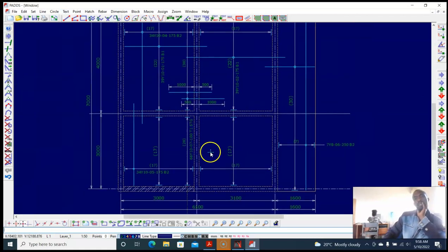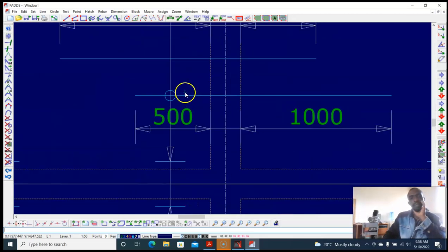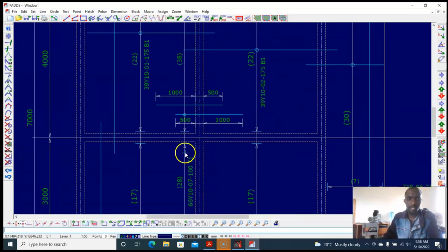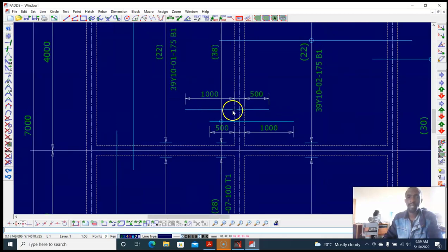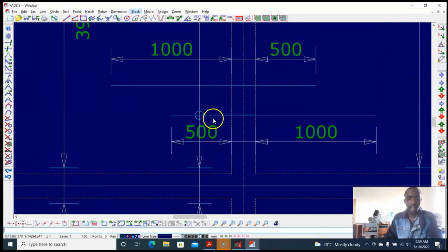Staggered. Repeat how you include that one and how you edit the text. We were at that point. This dimension line is picking this rebar, but it's not capturing this other one. So I type BB, pick this, click here, click there, B3, escape.